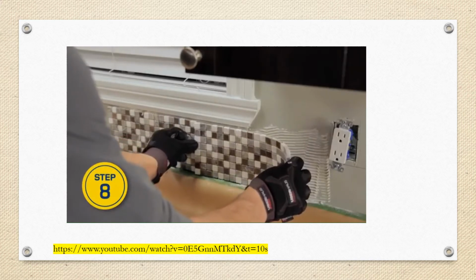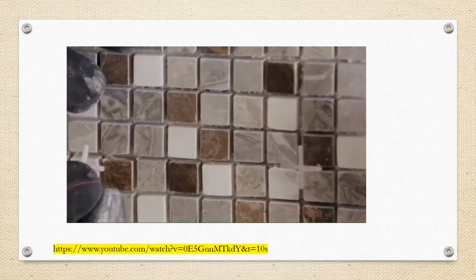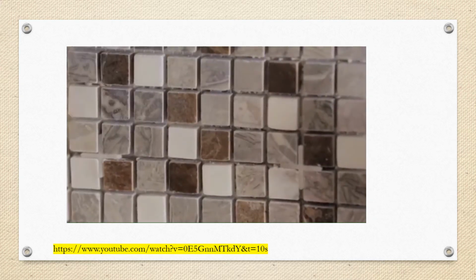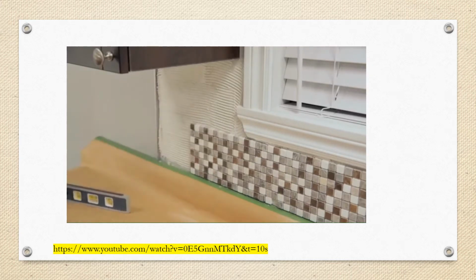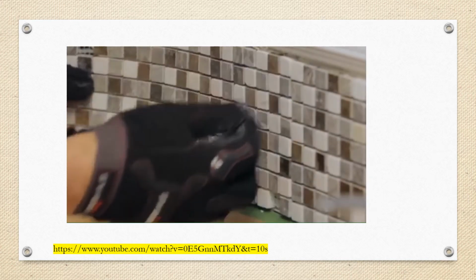Continue installing the first row of mosaic tile sheets, working from the center of the wall outwards. Separate each sheet with tile spacers to ensure even spacing. The gap between each sheet should be the same width as the gap between the individual tiles. With a level, check that the tiles are flat and even. Adjust with a rubber mallet if necessary. Cover the entire surface section by section.